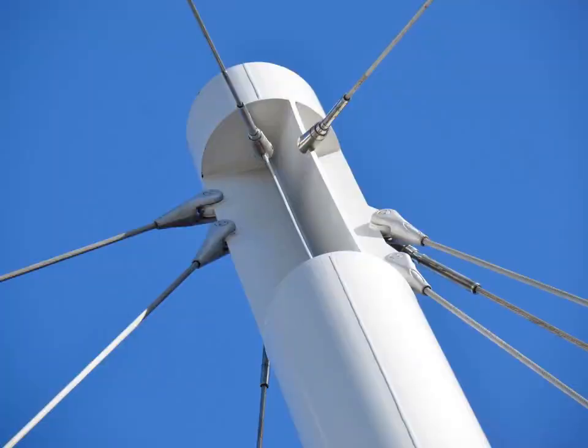The detail at the top of the mast is designed to accommodate the attachment of the clevises. You can see that the plates are differently sized to respond to the loading. Also, the plates have been thickened precisely where the clevis overlaps to provide the additional steel that is required to resist pull-through forces.